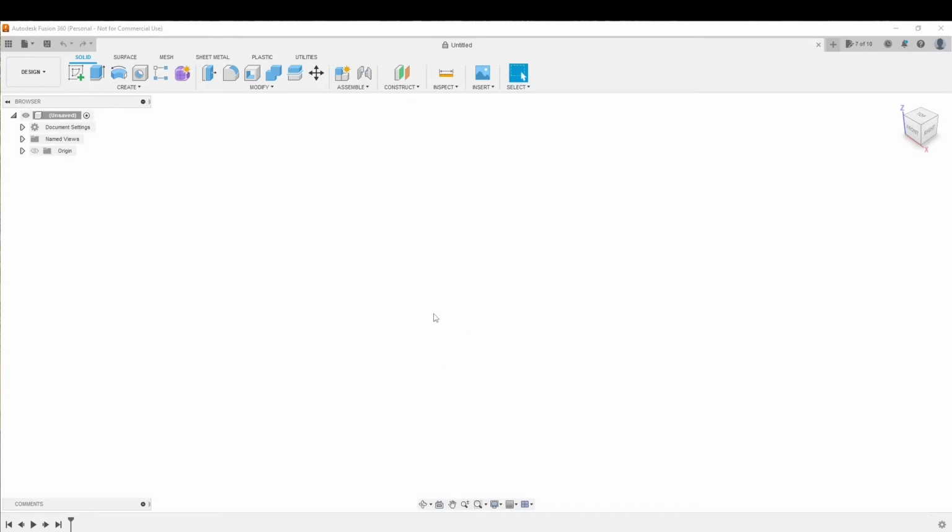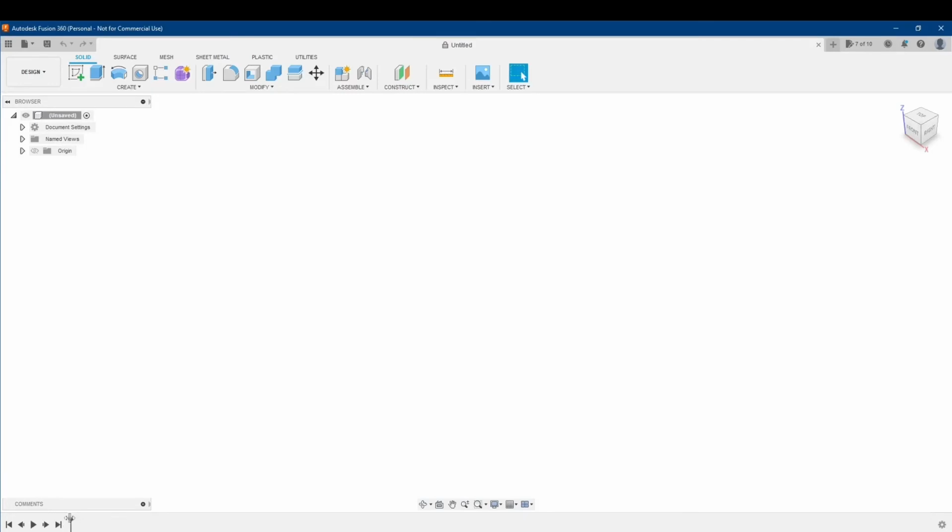So as you're making sketches or building models, editing them, all those actions will be recorded down here, and you can go forward or back in your timeline to specific steps. You can do it with this slider here, which isn't going to slide right now because there's nothing here. It can be an interesting tool to help you try to figure out what to do with your design.